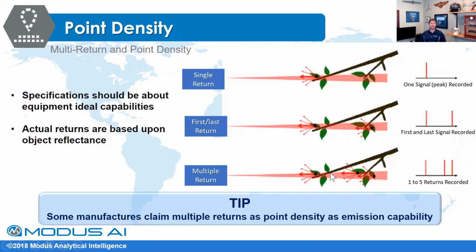All right, and the last piece of this is two different schemes that are going on in the LiDAR world. We have Riegl that sends out a signal and can get multiple returns by multi-sampling the same data stream that comes back. So it's a slightly better receiver. Where Velodyne, which was originally an auto sensor, uses a first and last scheme, and some people use just a single pulse.